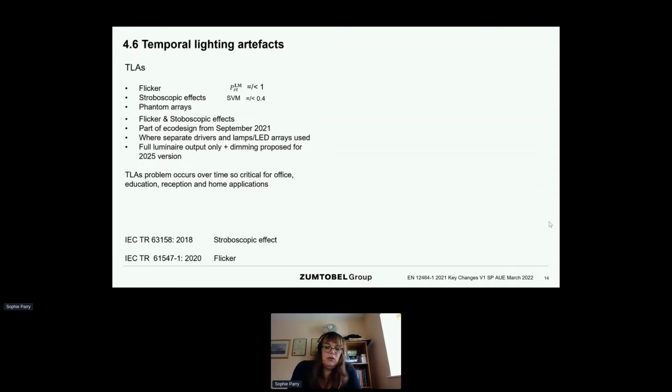So it's important really to look at a luminaire at the specification stage and say, well, what are the flicker properties? If somebody tells you they're offering you a luminaire that is flicker free, treat that very, very carefully. There is, in my opinion, no such thing as a flicker free luminaire. Only luminaires that have either got a flicker problem or luminaires where the flicker potential has been reduced to acceptable limits. So probably the only LED products you're going to find that can be claimed to be flicker free are a battery torch or an emergency light after the mains has gone off with an LED light source in it. So be very careful with that one and the claims that are made.